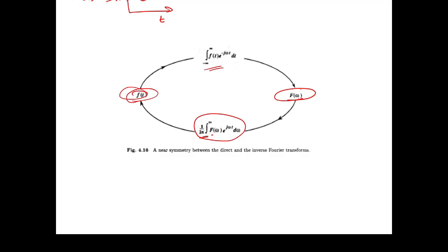But what are the frequency components hidden in this plot? We don't know. So if you apply the Fourier transform, we get a frequency versus amplitude plot, and at whatever frequencies the signal components are there, you will get some amplitude values over there.